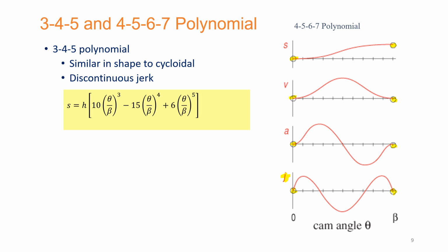So now you can obviously see that on this line you have 1, 2, 3, and 4 boundary conditions, and corresponding to this extreme you have 5, 6, 7, and 8 boundary conditions as well. So when you have 8 boundary conditions, obviously you are going to use 7th order polynomial in your case. And this is exactly what we are going to do.